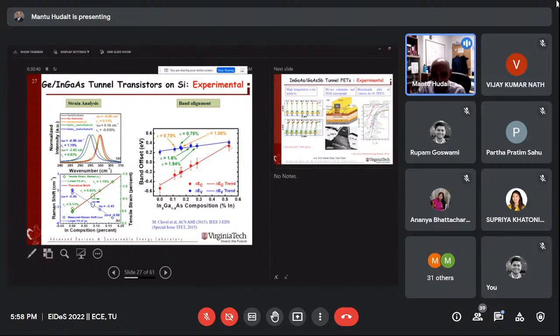So that is good. That means we did a lot of circuit and other stuff. What we couldn't do is get a real tunnel FET working, because we don't have an E-beam lithography, and tunnel diode long devices don't work. You need device dimensions of about 20, 30, 40, 50 nanometers, and we don't have that in our school. So we are kind of struggling every day.